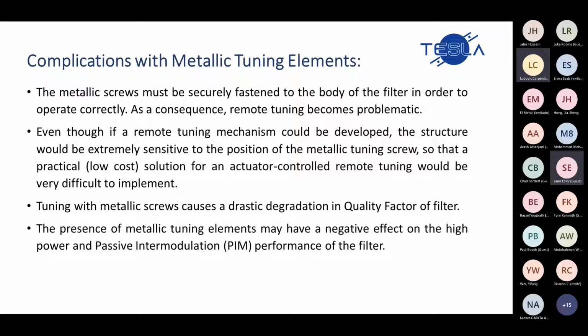In our approach, we are generally dealing with dielectric or metallic tuning elements. There are some complications which we have observed with the metallic tuning elements. When we tune the filter using a metallic screw, it has to be securely fastened to the body of the filter in order to operate correctly. That makes this method very complicated for remote tuning, because it has to be in contact with the filter structure all the time.